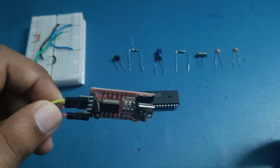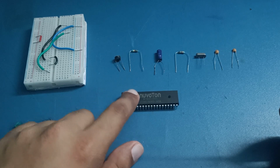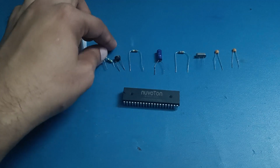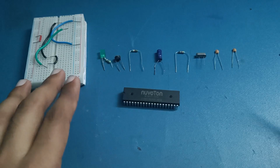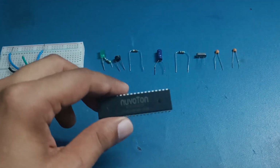This is detected by our COM port, and the flash software that we are going to use to burn the program into this chip is provided by Nuvoton for free. All we need to do is generate a hex file using Keil. I'm going to show you that later. So let's first make the circuit. Let's see what components we are going to need.